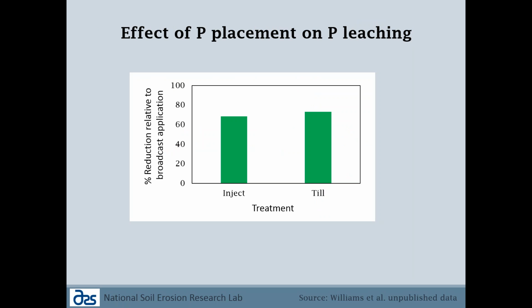And while there are a lot of benefits to no-till, I think it's important that we don't just go out and start tilling all our fields, because that is how we reduced our total phosphorus loads to Lake Erie. But there are unintended consequences of no-till that may increase dissolved phosphorus loading through stratification and broadcast fertilizer application. So we've done a recent follow-up study on this, looking at injecting our dry fertilizers versus tilling them in.